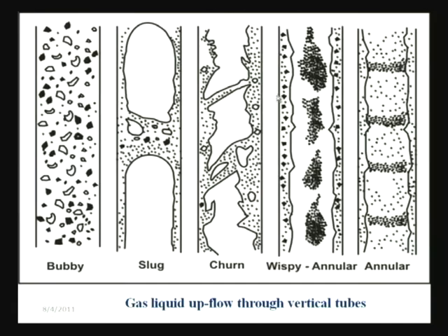Okay. And sometimes this film is usually wavy. When it is wavy, then part of this particular film is entrained by the gas phase and it flows as droplets or as irregular chunks or irregular wisps in the gas core.